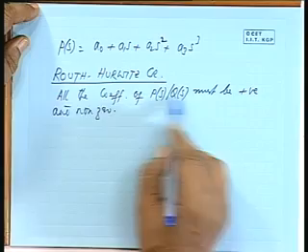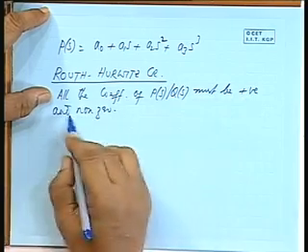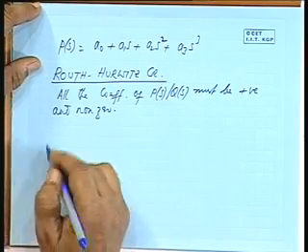For an LC network, for example, you will have functions Z(s) or Y(s) where you get s squared plus omega 1 squared, s squared plus omega 2 squared, and so on, and one will be even, the other odd. That is possible. That is an exception, where alternate terms are absent. So for the general case all the coefficients must be positive and non-zero.